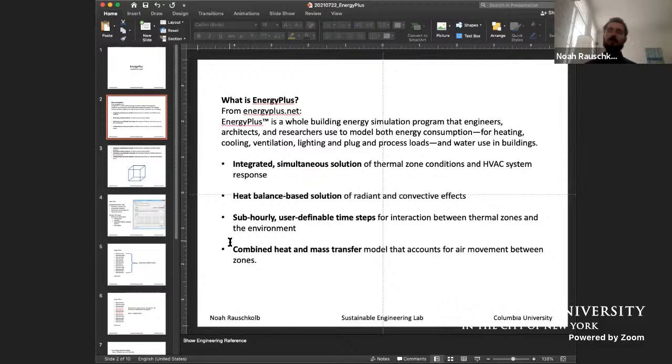And that could be just a set point or a dead band, trying to keep the temperature between 68 and 72. It can model humidity sensors. So you could, in theory, have an air conditioning system that's trying to keep both the temperature and the humidity within certain ranges, and it will model how that system responds mechanically to all of these things happening on the outside of the building, as well as internal loads. If you've got people in the building, we produce both sensible and latent heat.